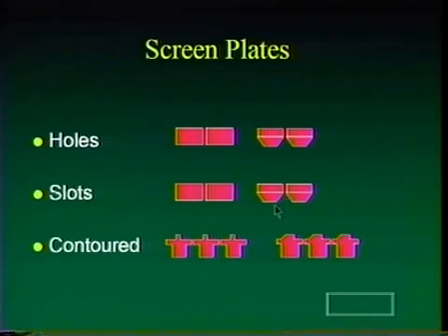Now the other thing that you'll notice, for slots at least, quite a bit, is you won't have a flat surface on the feed side of your faceplate. What you will have is some contour. Here we're showing some bumps, and here's another type of bump. In this case, the pulp would be flowing from left to right, and these bumps are there to cause microturbulence.